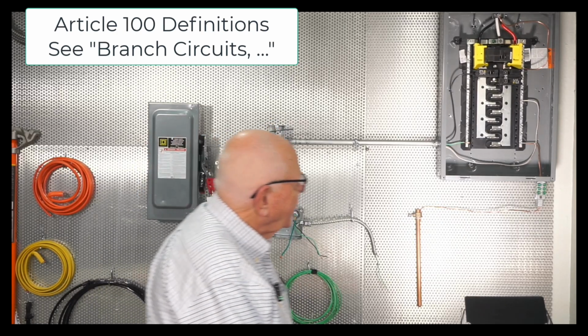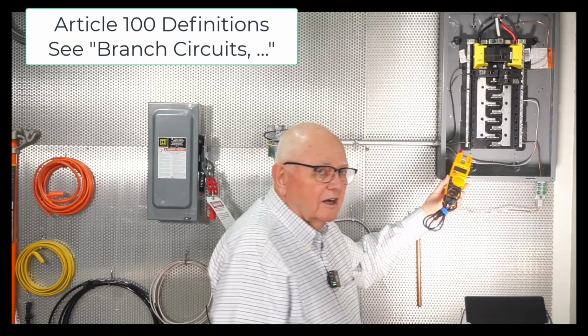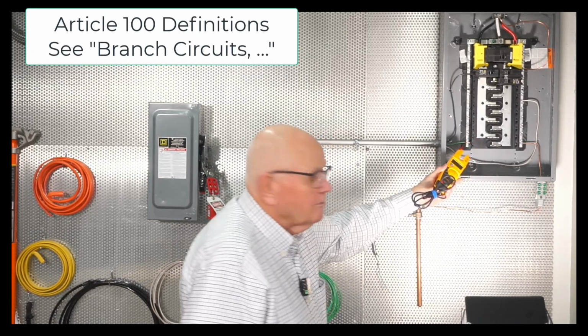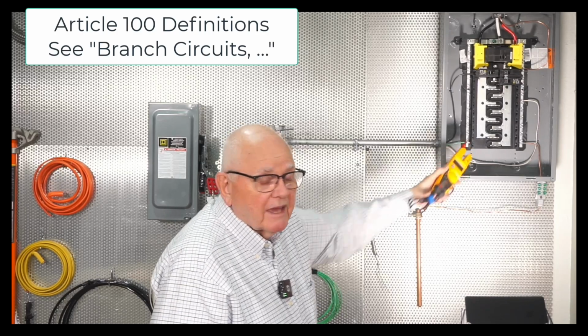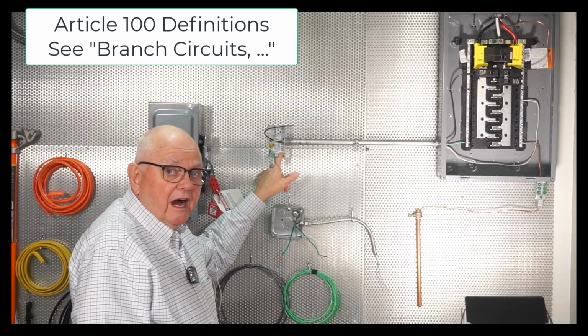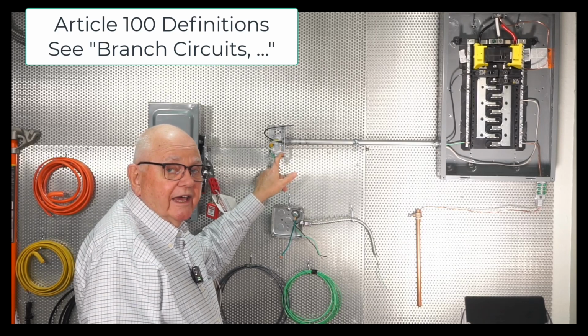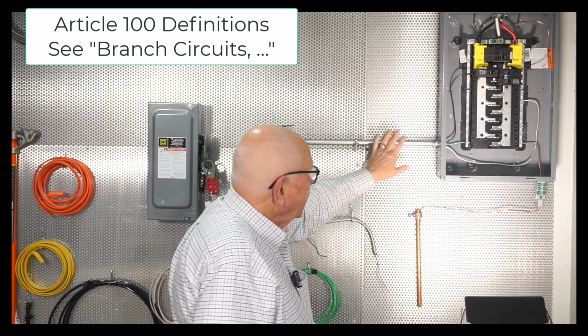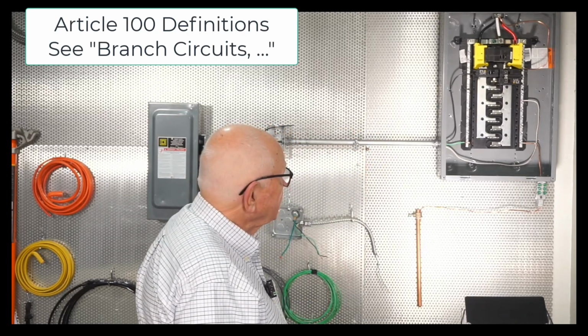And then of course I have my equipment grounding conductor, the conductor with the green insulation on it, and that runs from my equipment grounding bus bar on my panel board, out to my metal box, which I have gone ahead and bonded to my metal box, and I'm using some EMT, electrical metallic tubing today.